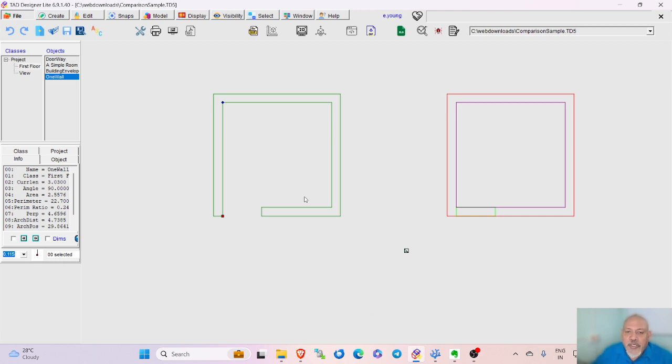Suppose I want to take the area of the room. What normally people would do in such a situation is that they will simply click in the corners of this room, and then it will give out the area. In recent CAD software, you probably can click in the interior of the room, and it can figure out what you are wanting. But in cases like this, where the interior escapes through the doorway, it may lead to an error. So the only way then is to click once again in sequence all those points, and then you will get the area of that room.